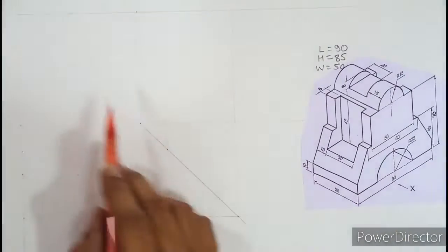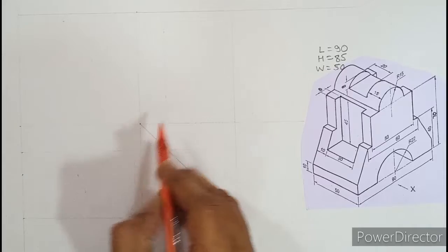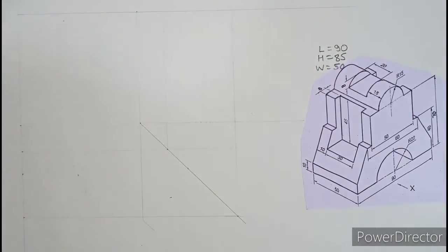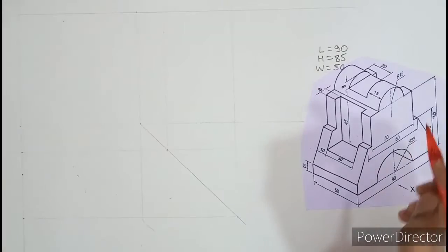So that is how the three boxes are ready. This is the side view box which I have drawn without measurement. So only with the help of the 45-degree line I can easily complete the side view box. Okay, so let us now start with this particular question.